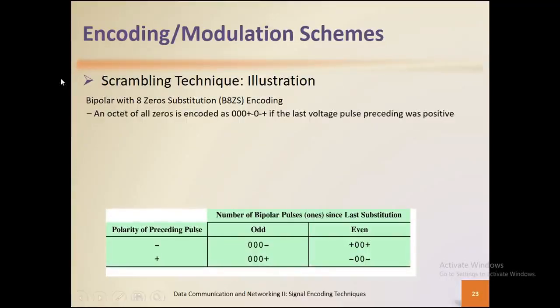The coding scheme is usually based on the standardized bipolar AMI implementation and the multi-level binary techniques. So you can have 3-level signaling voltage levels within the bipolar or multi-level binary encoding scheme.